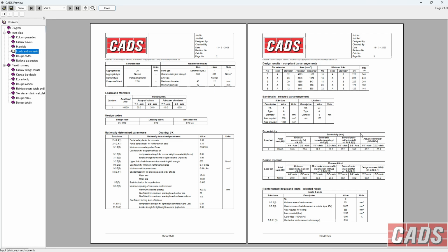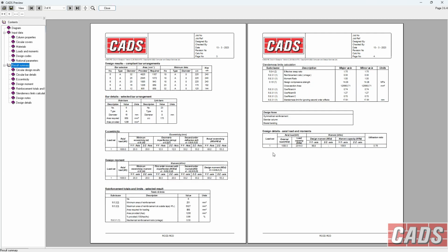Now this is where the extra work is done in the Eurocode. All these other moments that are calculated for different eccentricities applied for minimum eccentricity, geometric imperfection for lack of plumb. That's where the 1 in 200 comes in. And then the second order effects are working here because it's a slender column.